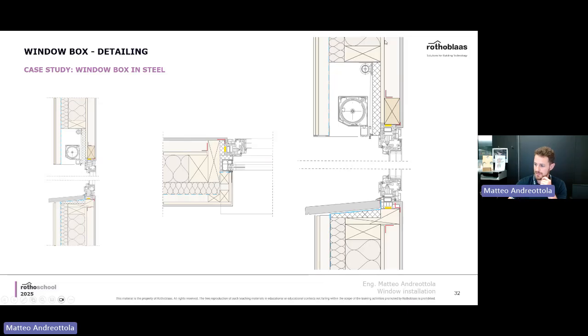In this design, you potentially have a little bit of cold bridge going up through the detail here. So it would be better to have something different. This one, I don't like so much. You see immediately potential issues coming here, interstitial condensation, and so on and so forth.